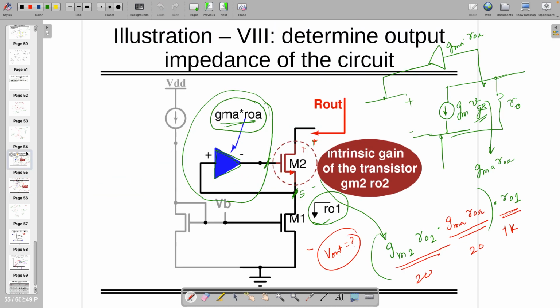If you remember, somewhere I wrote 400 kilo. I don't like 400 kilo of resistance. The oscilloscope or the DSO which we are using in our laboratory has an input impedance of 1 mega. We have to match that 1 mega. If here itself it is 400 kilo, then 1 mega is actually not so useful, right? So you have to have higher and higher impedance.